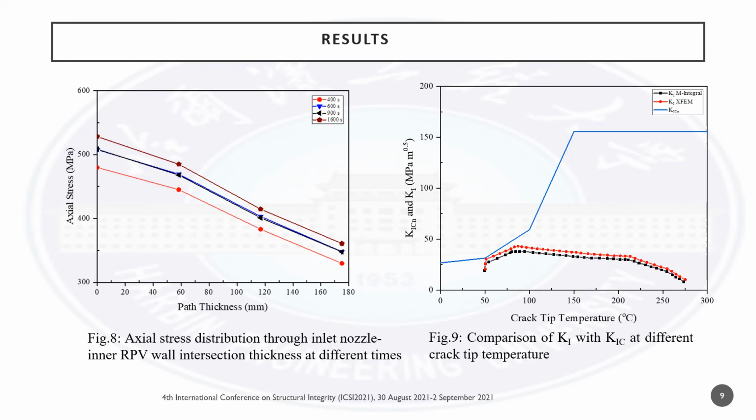However, the fracture toughness of the material of the vessel was higher than the integrity parameter determined, which in this case is the stress intensity factor. This indicates that an inadvertent operation of safety injection would have less impact on the structural integrity of the reactor pressure vessel.